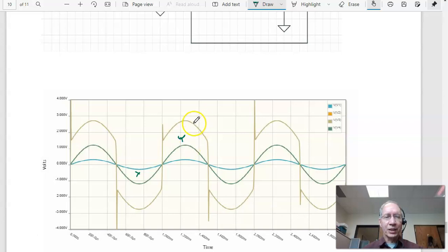And this is the voltage at the base. So up here, I'm doing push, it's the output plus VBE. Over here I'm doing pull, the PNPs turn on. You can spell pull right, P-U-L-L, there we go, pull, is this voltage minus VBE. And when the output is 0, again, I'm somewhere on this line. I'm not really sure what the base voltage is. It's somewhere between minus VBE and plus VBE.